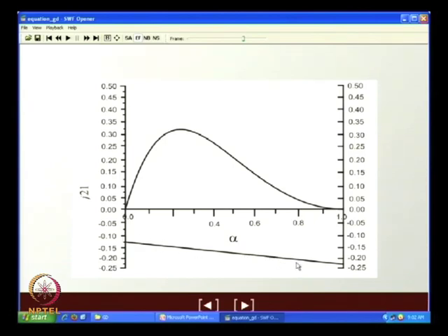Well, now let us go to the final operation. It was countercurrent operation with gas down, liquid up. Gas down means J2 is negative, liquid up means J1 is positive, minus J1 is negative. So, that means both J2 is negative and minus J1 is negative. Therefore, the straight line will lie in the fourth quadrant, is not it? The straight line will be something of this sort. And if you observe this particular PPT, you find that the straight line will lie here.